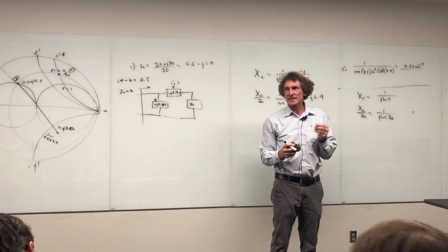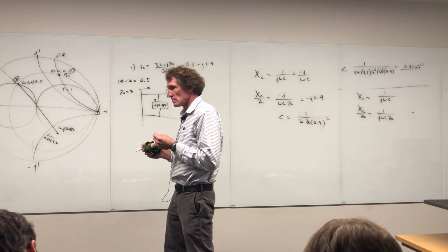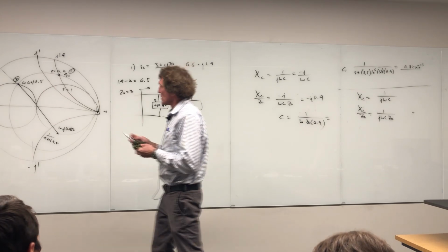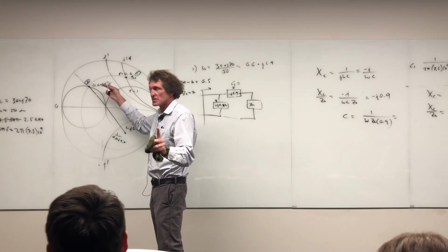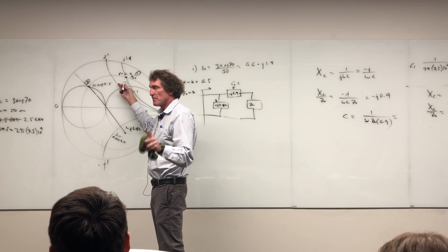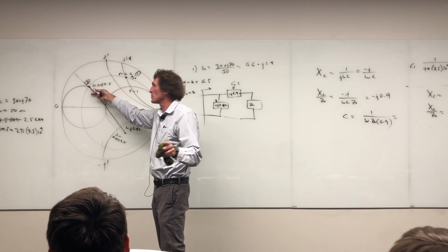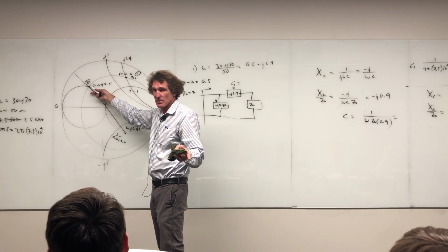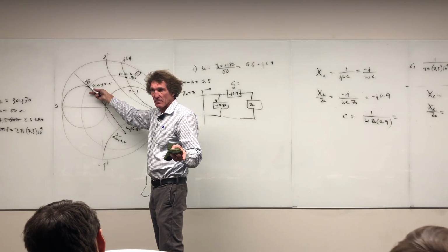Now once we do this, yeah. Sorry, one question. You went from 1 to 2, that was the first capacitor? The first capacitor takes us from here to here. Because remember, this is the impedance domain, right? Impedance, we add in series, right? And we want to go from this point to this point. We're always trying to get to the rotated circle. That's the bottom line. And that's the reason I went that way.